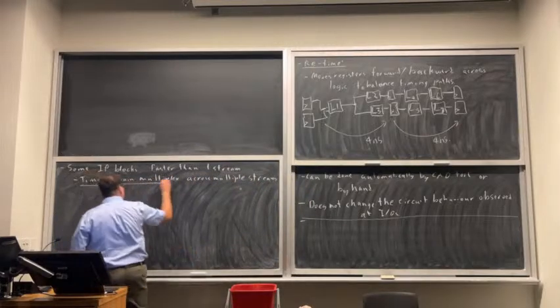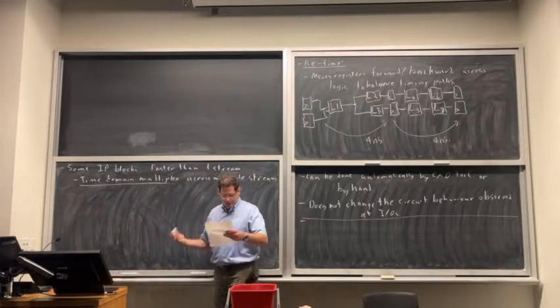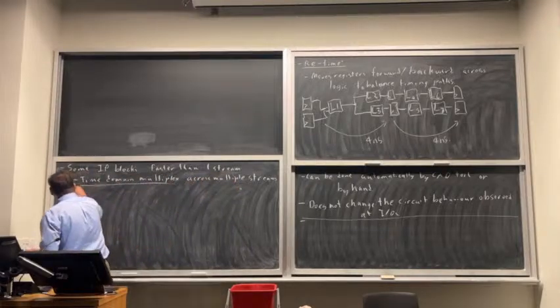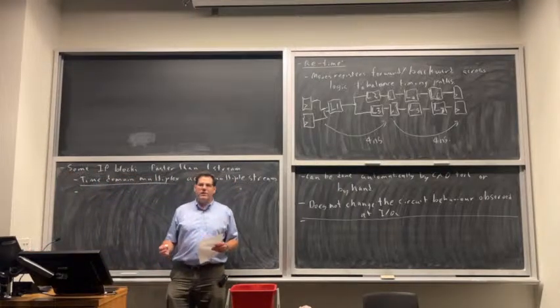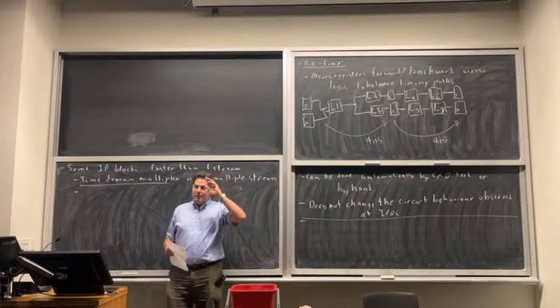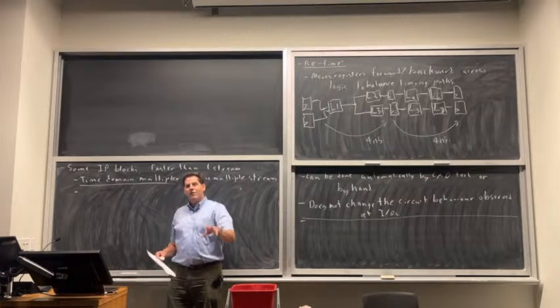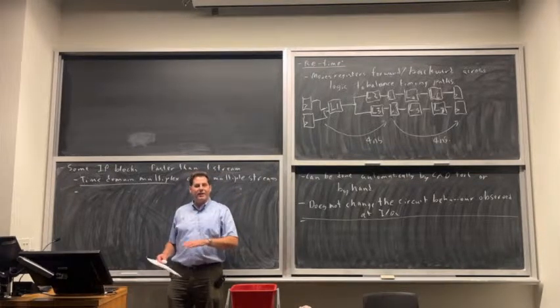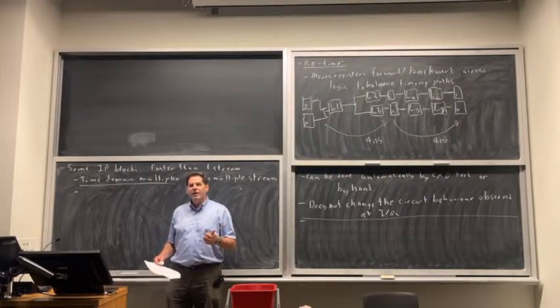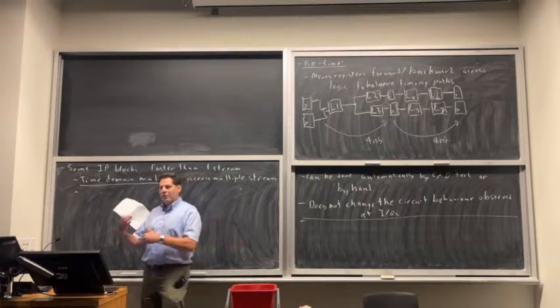Okay, so time domain multiplexing is like another class of optimizations. And the good way to do this is just like we did with valid bits and ready bits, where your control is distributed. You're tagging your data. We've already tagged data with valid if we needed that, and we can have ready to say whether we should back pressure or not.